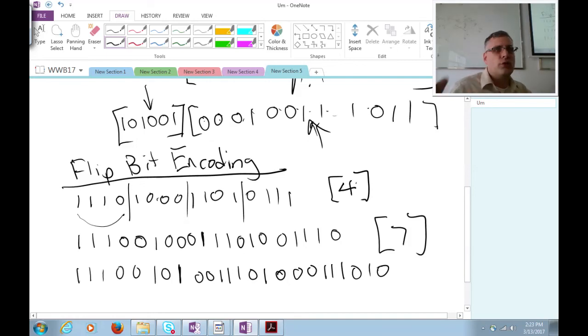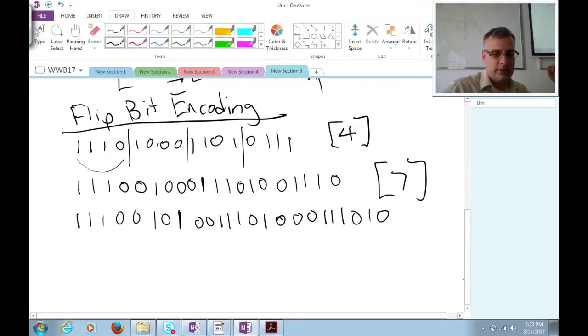So you could run that 2 or 3 or 4 times, and it would be very simple to build hardware that could keep track of whether you have too many 1s or too many 0s in a sequence, and just append simple bits. So from a complexity point of view, it'd be very low. The real question is just, is this enough content that you can remove from the signal to make it detectable in a backscatter system? And that's a really interesting question to explore. It would make a good project or something like this. So even if you want to invent your own encoding technique, this would be an interesting topic to explore.